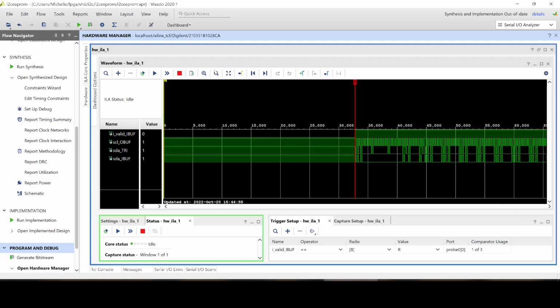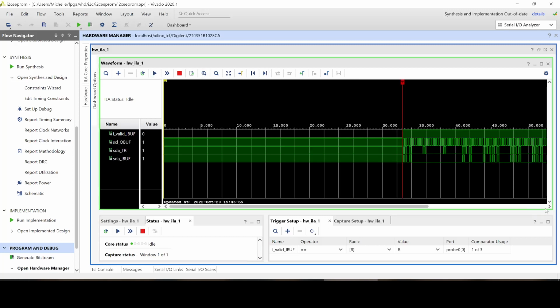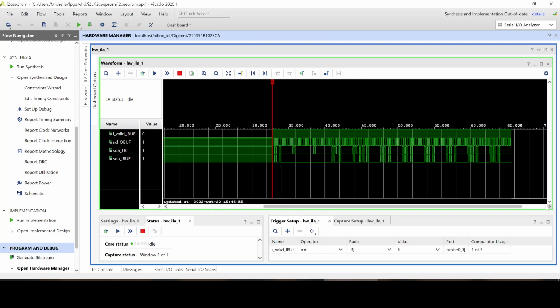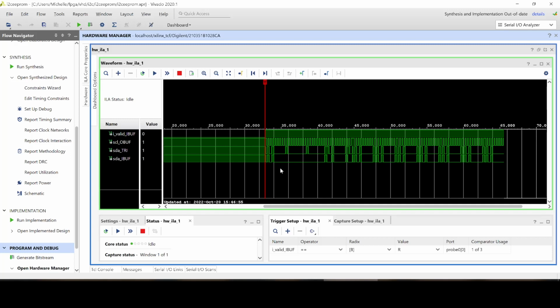Let's zoom in a little bit. Yeah, we need to zoom in a little bit here. And then let's move this over so we can take a look at what the FPGA did. It was just like our sim. We basically did a 1, 0, 1, 0, 0, 0. Here was our high impedance, and here's our 0 data for acknowledgement. So we got our acknowledgement from our slave.